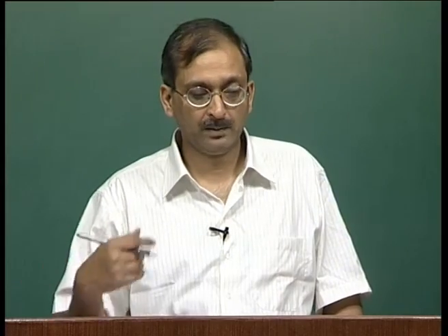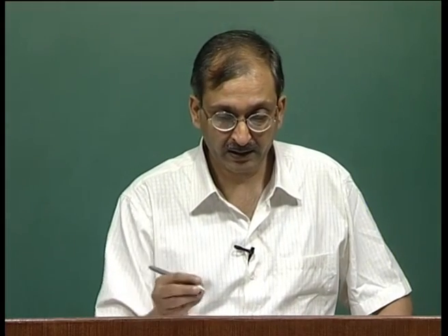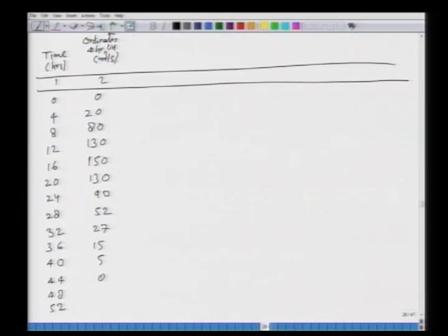Of course, if we did that, we can get the same answer, but we will use a very compact method. What we do is we develop 2 columns, and in developing only these 2 columns, we will get the S curve. The next one is what is called the S curve addition column, and this is also in meter cube per second.